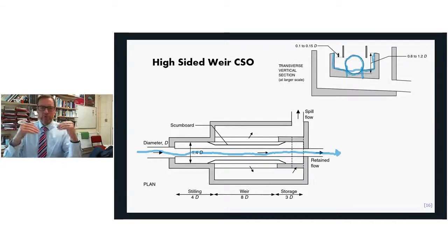The slope's important because once the flow goes back to more dry weather flow conditions again, any solid particles which have deposited on those slope sides are then hopefully washed back into the channel and go to treatment. So what happens during rainfall events is that the flow comes in through the circular pipe, top right again, and it begins to rise.